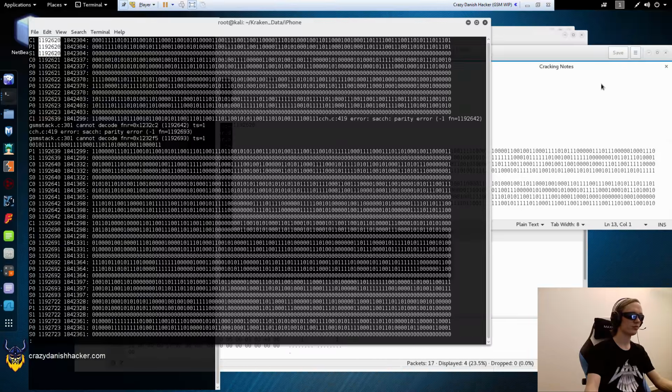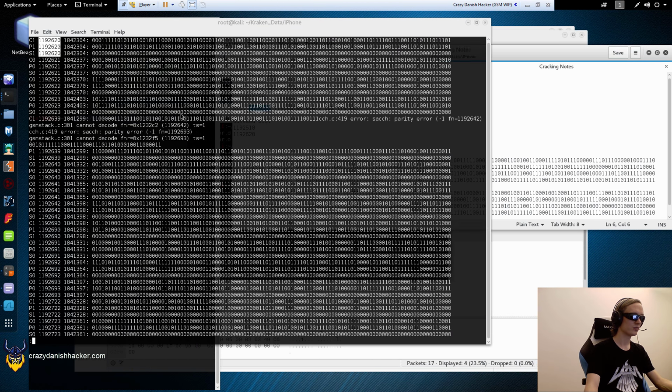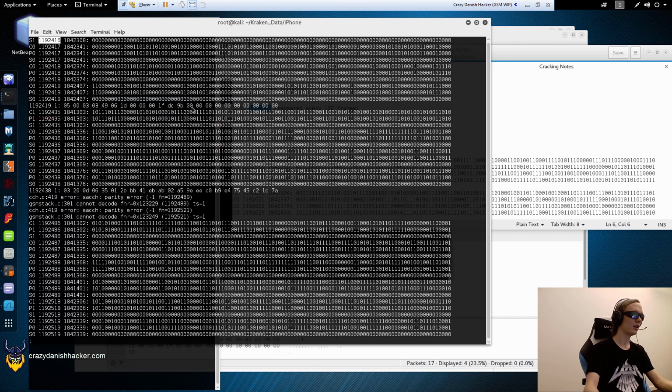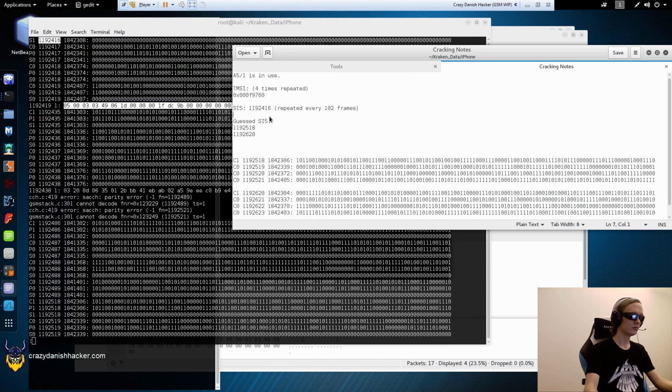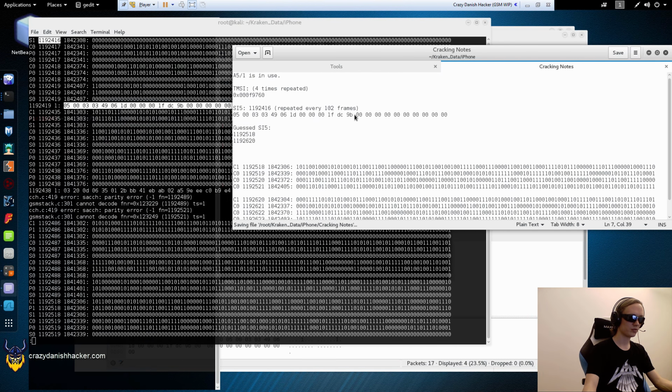And then we need to go back to this frame here. So we'll just use question mark because it's upwards. And then we will just copy these bytes here, because that is this packet, and I'll just confirm that there are enough bytes here. After 9B in my case, there should be 1000 bytes. So that's very important, because otherwise you will have to re-record your video because you screwed up by missing 1 byte.